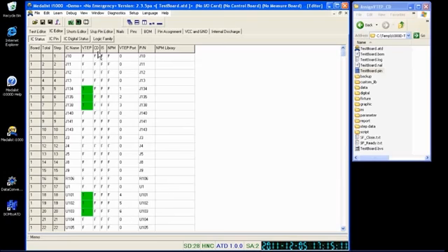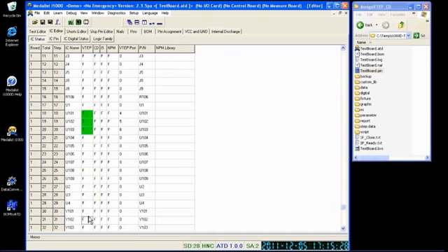The next thing to assign is the clamping diode test. The clamping diode test will be assigned under the column CD. CD stands for clamping diode. And basically, the clamping diode test only applies to ICs. So let's scroll down a little bit to get to the rest of the ICs. Again, assigning a clamping diode test is very straightforward. Under the CD column of the respective device, just type in a T and press Enter. T and press Enter. And there it goes.